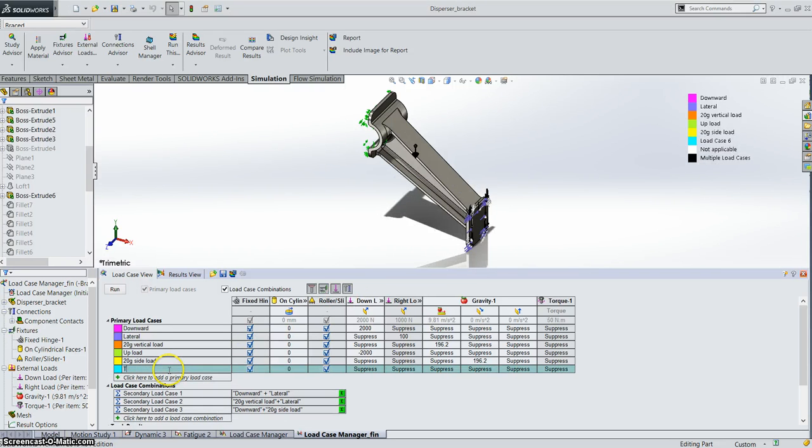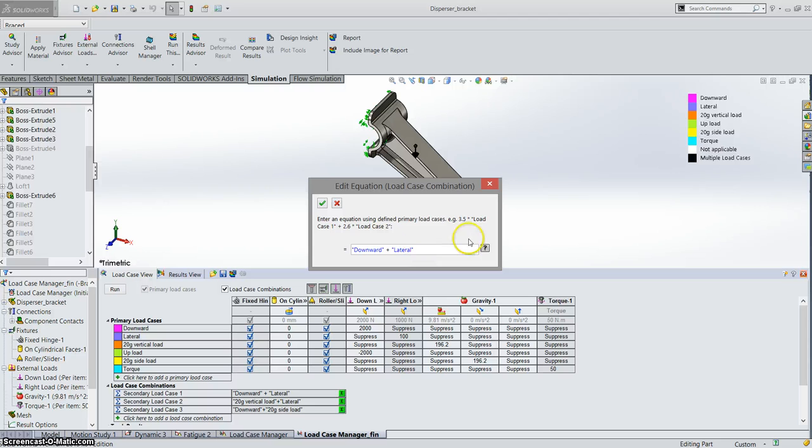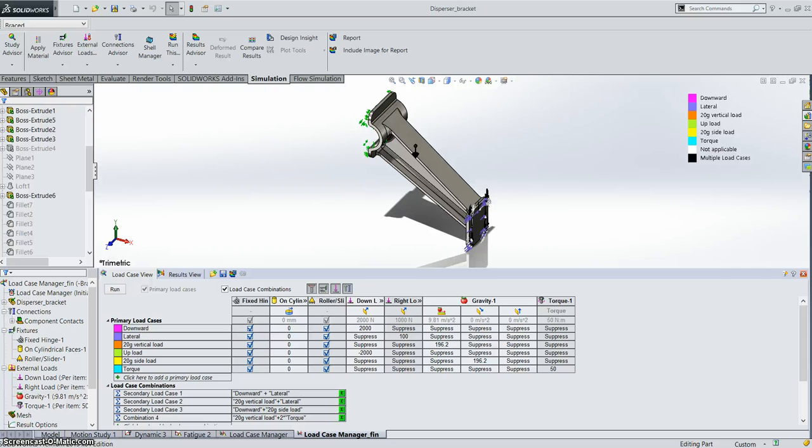And I'm going to go ahead and just add it so you can see exactly how to add one. So it's very simple, just a thing of typing. Over here I can select my torque, got 50. We even have these filters up here to show and hide the connectors, to look at the loads, any of the forces or fixtures, and even no filter at all. We can also do load case combinations, so if I click in here we can even use all different types of equations. So all of the information I've already given it, it's picked up on, and I can go ahead and use those to have a new load case. So we can go for our 20 gram vertical, that's 2 by our torque. We can use our equations and make everything very clever and very useful. You can also track some critical performance information using sensors and compare the performances across the load cases. What we're going to do now is run it and then we'll have a look at our results.